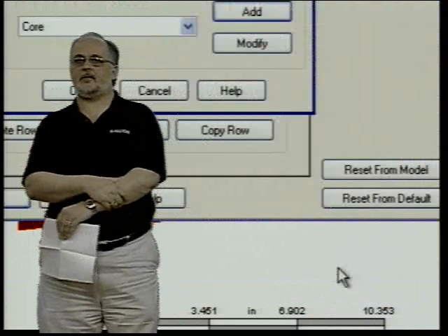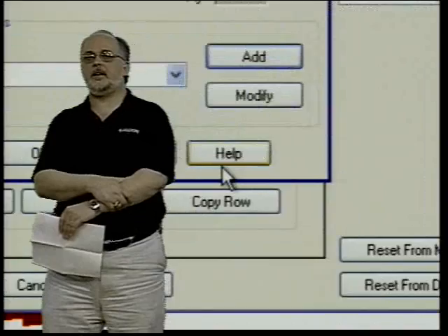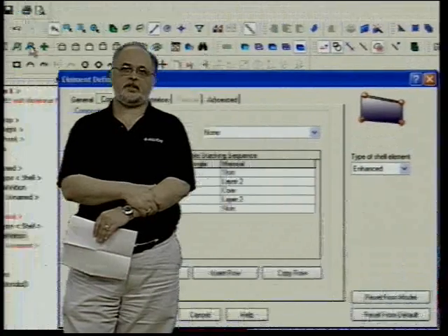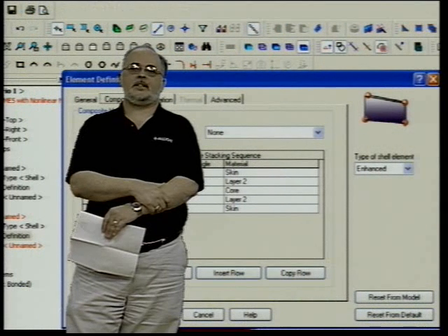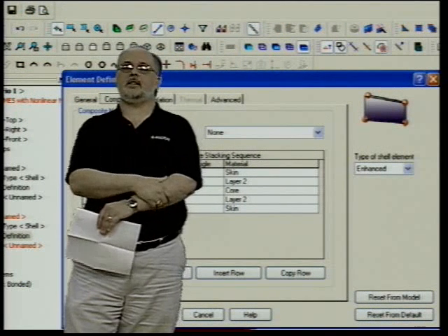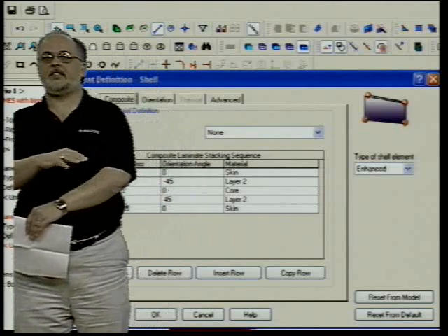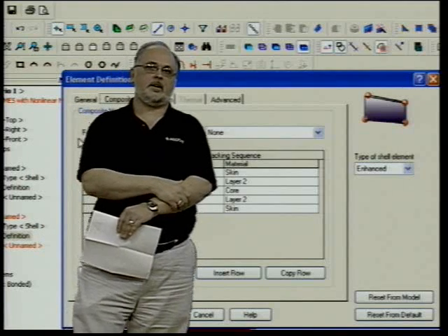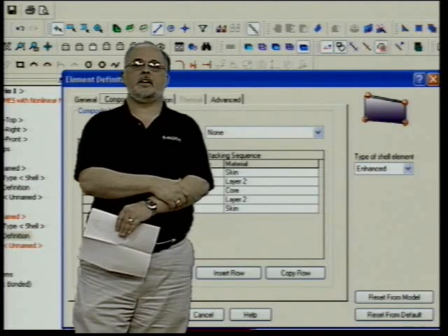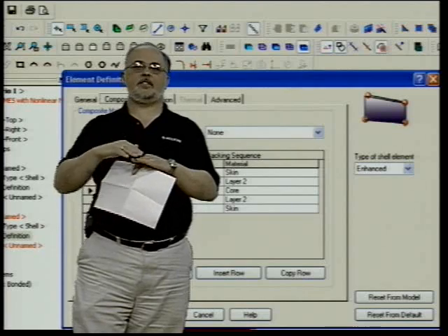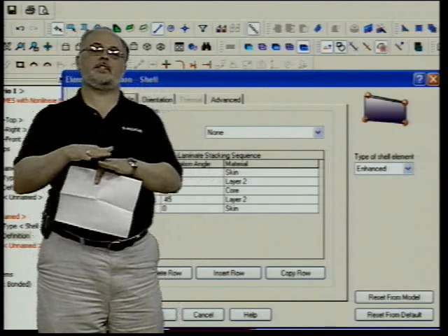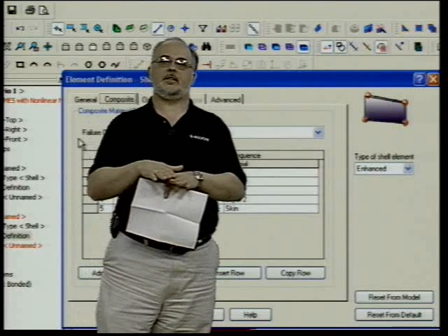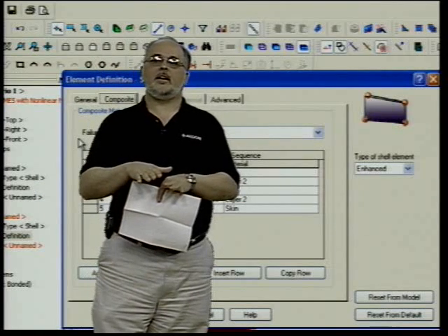Incidentally, before we go any further, a general comment while I'm thinking about it. There are a couple of different ways of handling composite materials, and one approach that's been taken is if you have a composite, a given stack up of material, say fiberglass type circuit board, glass epoxy or whatever, and you know the behavior of the sandwich of maybe 5 layers, but you know its behavior as a whole, you can treat it as a regular plate element or a regular shell element that's orthotropic.